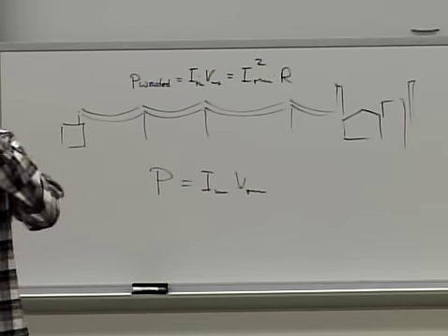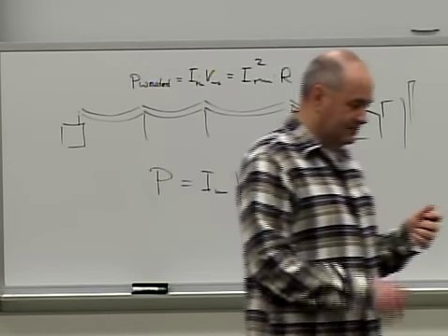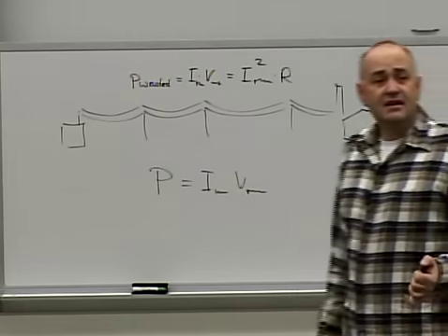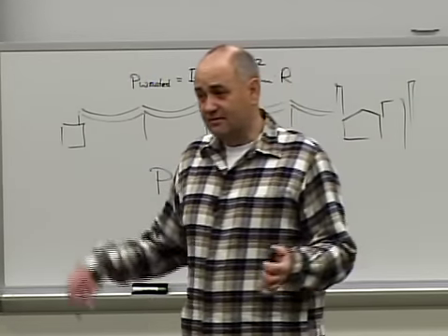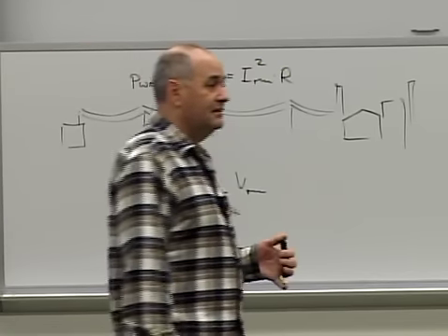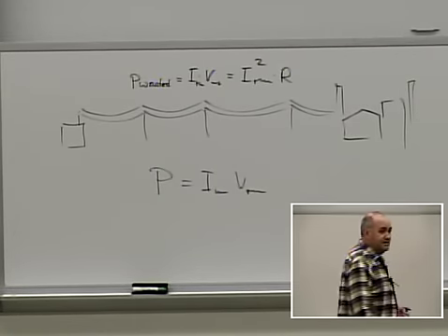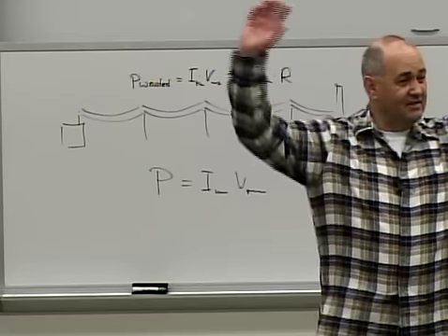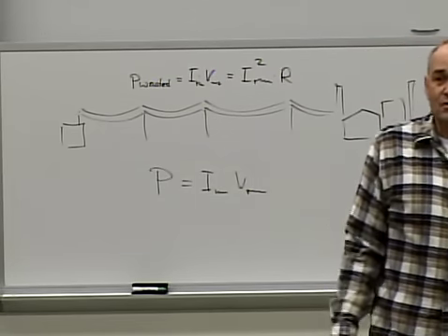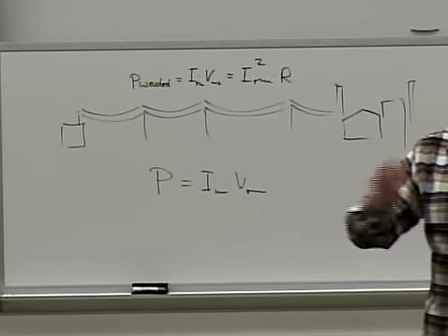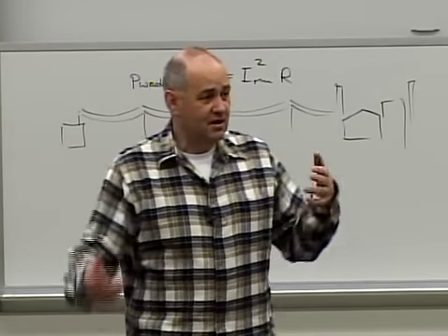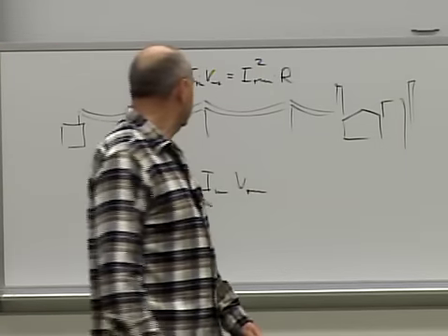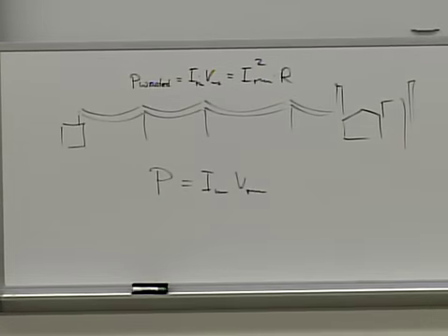Now we also have limitations, because obviously the higher the potential difference, the less energy is wasted. But we don't have technology to prevent dielectric breakdown of the air. So we would have to build the poles higher and separate the wires more and more. So we have to figure out where is the balance between the cost of building the power line and what potential difference we use.